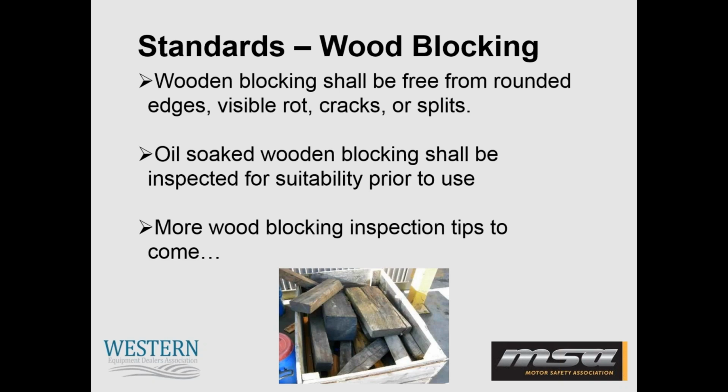Your blocking should be free from rounded edges, any visible rot, cracks, or splitting. A good practice is to store your wood blocking out of the weather elements in a clean, dry place. That will also help preserve your wood blocking. If you have oil-soaked wood blocking, it should be inspected for suitability prior to use.